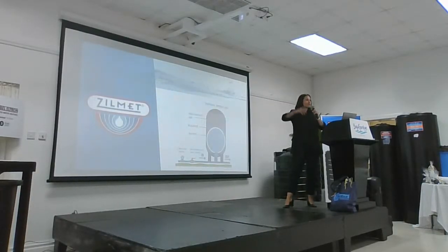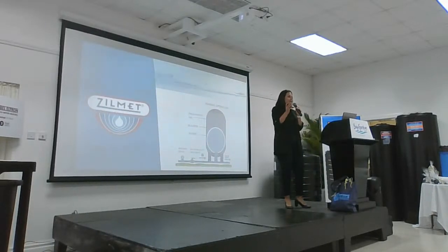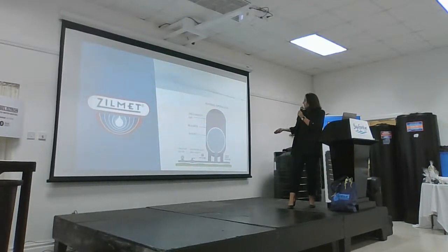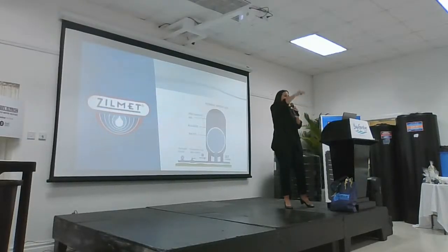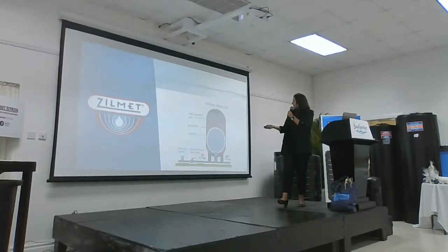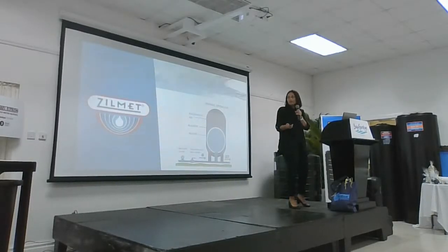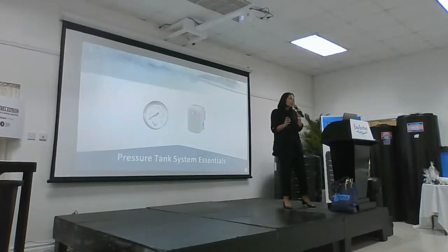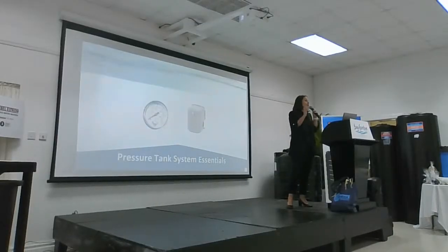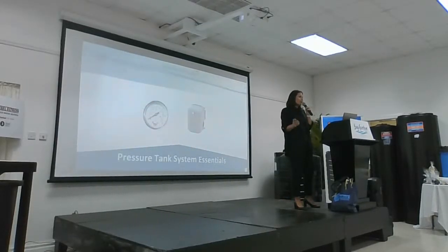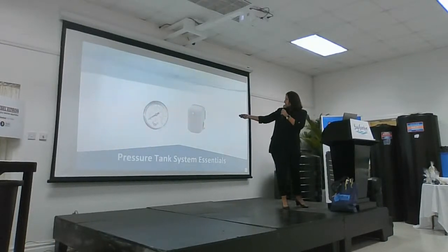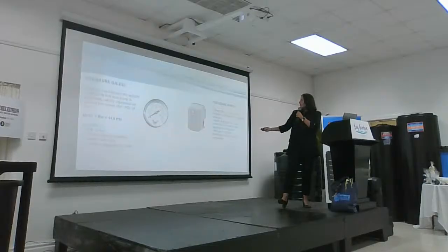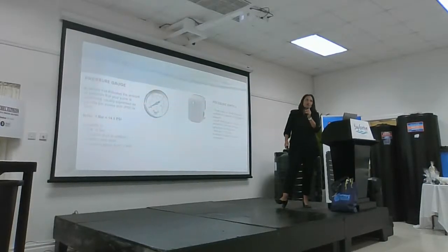With the 24-liter tanks and the 500-liter tanks that we carry, the setup is a little bit different. It comes with a bladder, which is essentially a balloon within the tank. So similarly, the air will be stored at the top and the water within the bladder. Of course, all pressure tank systems come with different components that are essential to making the system work. As mentioned, Rotoplastics does assemble these pumps with the pressure gauge, the pressure switch, as well as the flow switch.